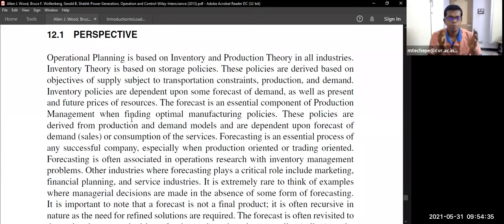So in that scenario, generation will drop if that load drop persists for more than half an hour or 1 hour, then definitely they will drop. They will not simply drop it if the load is very low for 5 minutes or 10 minutes. If the load demand is less for more than 1 hour, then they may call a particular generating station, whichever is more costly, and ask it to stop.